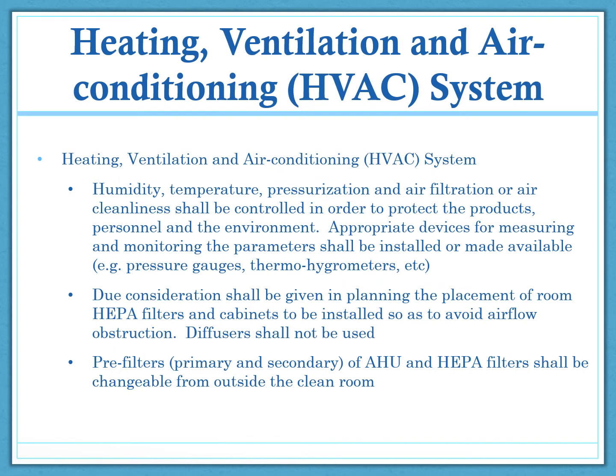So if we're looking into the HVAC system, obviously humidity, temperature, pressurization, as well as air filtration or air cleanliness shall be controlled in order to protect the product, personnel, and also the environment. And due consideration should be given in planning the placement of a room for HEPA filters and cabinets to be installed so as to avoid airflow obstruction, and diffusers shall not be used. Pre-filter, the primary and secondary of AHU and HEPA filters shall be changeable from outside the clean room, and the records need to be maintained.